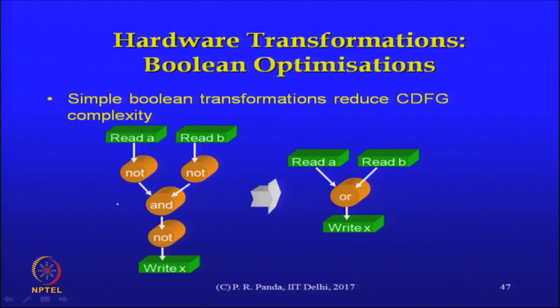There are rules from Boolean logic that could be used to simplify parts of our expressions. Say there is some function that may be applied to bit vectors as opposed to bits. If it is simple bits, then it is all right; it will get optimized out at some stage when you do logic synthesis. But some of those rules of Boolean logic, particularly the ones that extend to bit vectors as opposed to just bits, can be used to perform some simplifications.